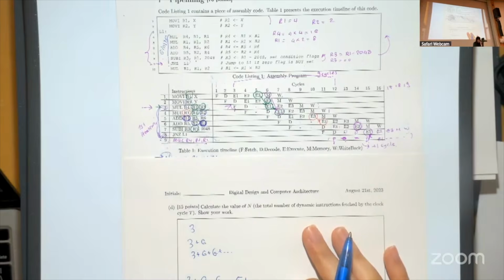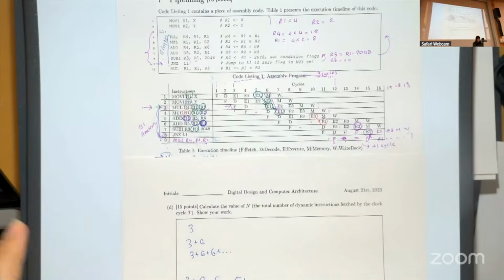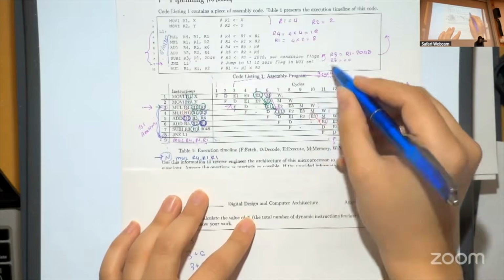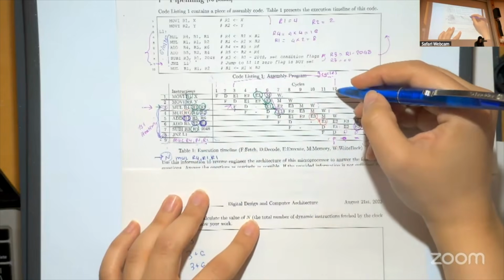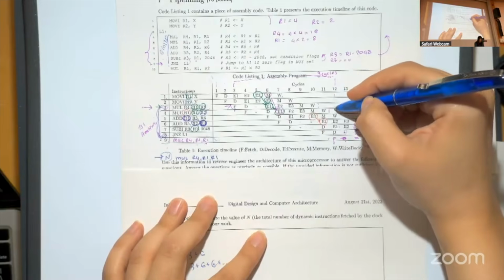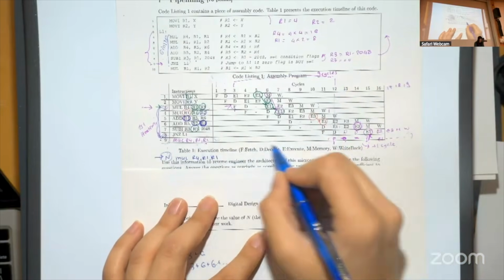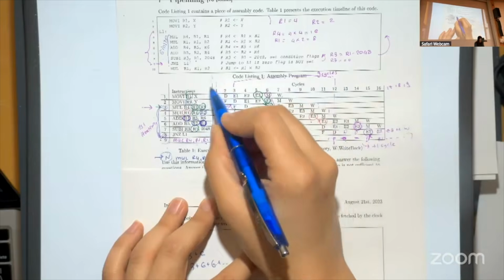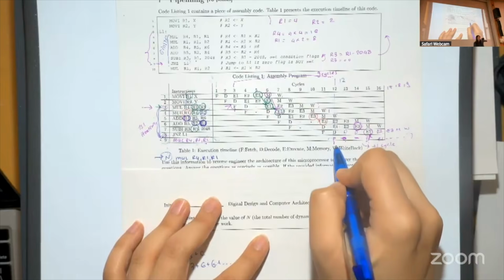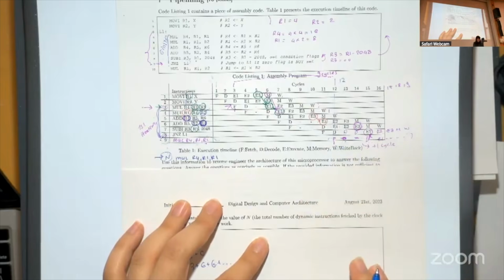There are two ways to do this, and I'm confused about which one to follow. So let's use this calculation. Here, what we did is we calculated the time it takes for us to get until the second iteration of the loop. So with also including the initialization, it takes 12 cycles. And after that point, we need to execute the loop 7 times.